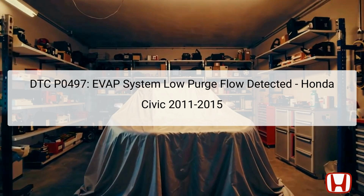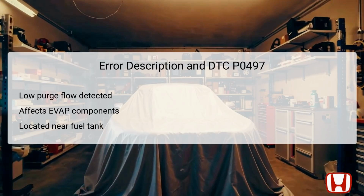Accurate diagnosis is essential, as this issue can affect vehicle performance as well as the environment by leading to increased emissions. DTC P0497 pertains to the EVAP system's inability to maintain proper purge flow levels. This means that the system isn't effectively venting fuel vapors as designed, potentially leading to increased emissions.